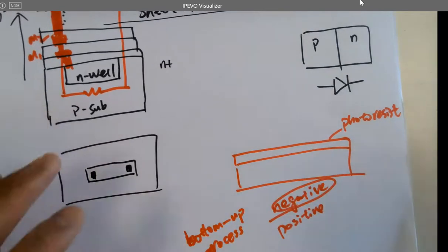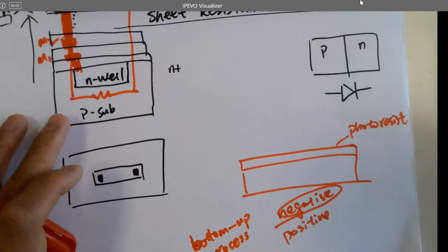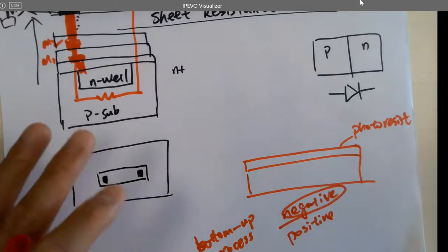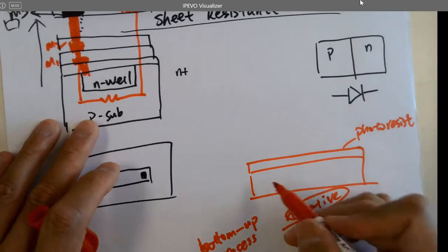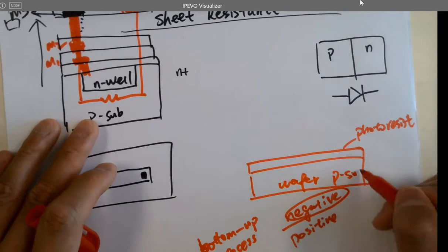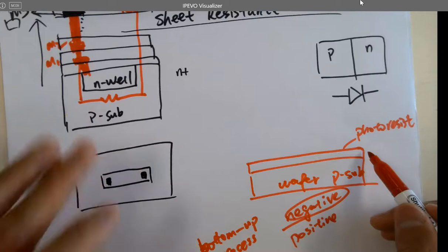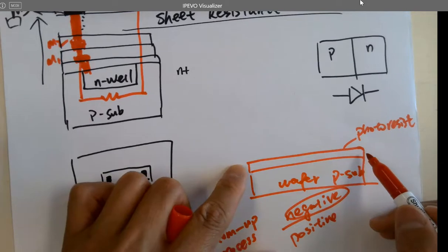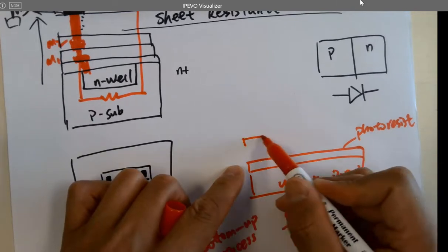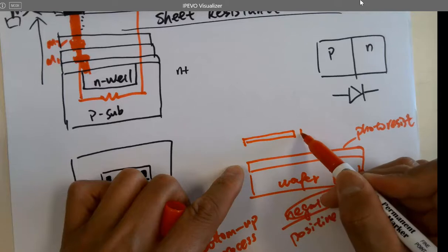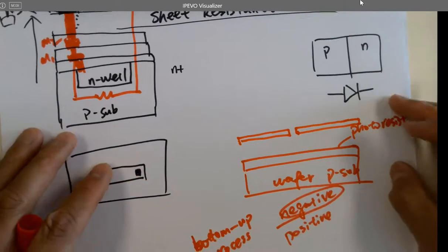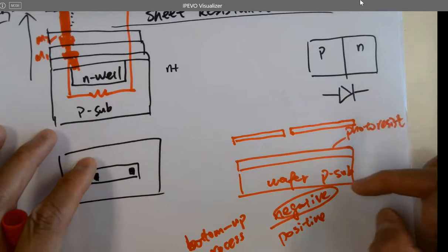Now let's just do a very simple photolithography. You will understand since you have been doing that manually in the lab. Very similar, okay? So first, here's a wafer or substrate, and I spin coat a photoresist material on the top. And here's my mask. I just place the mask. So the mask, you can design the mask for the IC chip where?